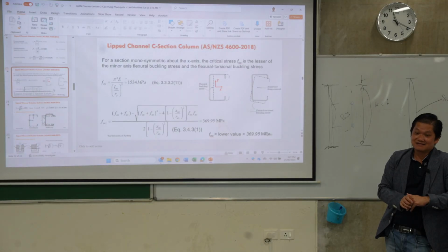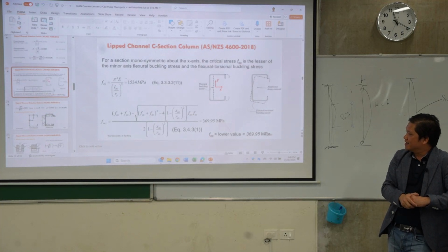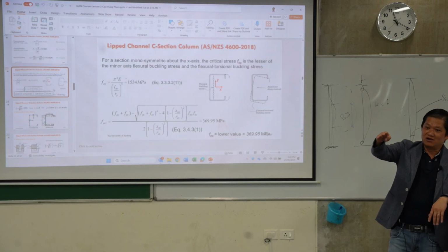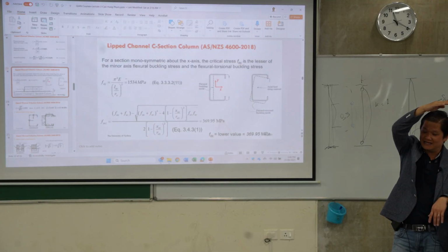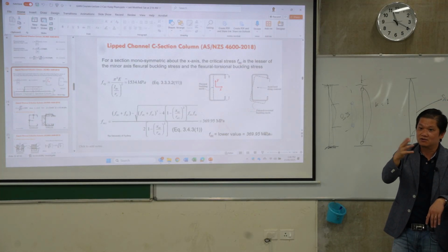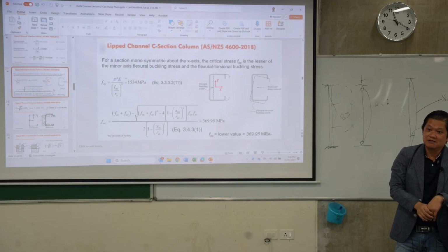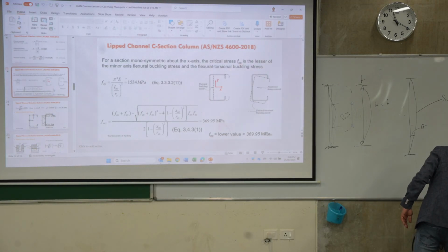Is the discussion whether the section may go to the plastic state? At the moment it's similar. Everything happens when it buckles. It's not going to the plasticity or the compact section. Yes, you can design that. There's a rule in the DSM equation for that range, and you can design for that.